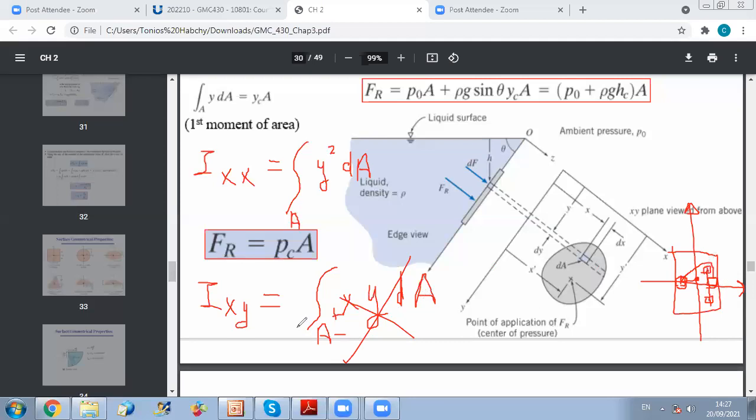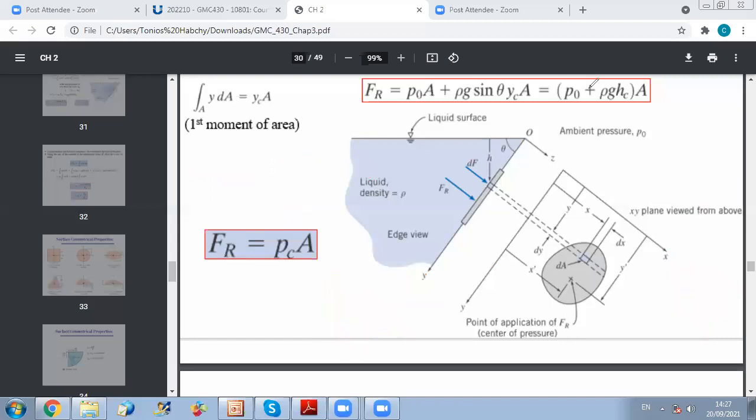So when I do the addition over the whole area, these two element terms cancel out. So it's enough to have just one of them as an axis of symmetry to ensure 0 for Ixy. And of course, for the rectangle, both axes are axes of symmetry, so automatically Ixy is 0. Okay? Yes, doctor, thank you. Welcome.